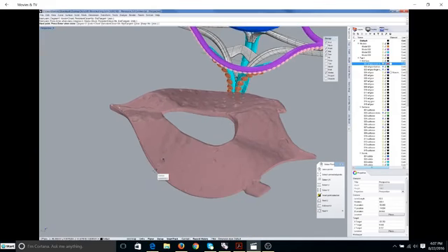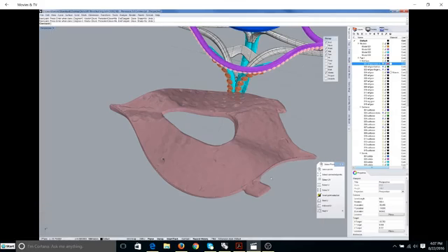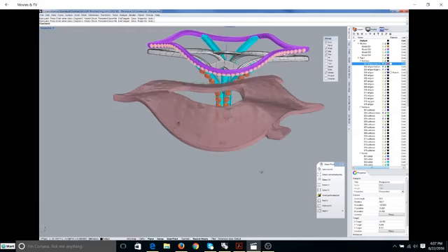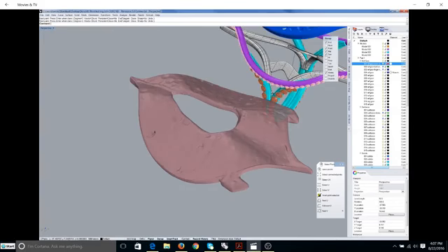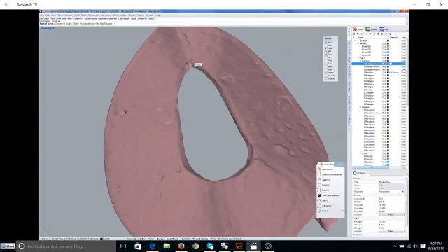And again, I'm going to do this down and dirty. This is not a Rhino class. It's just a demo to show how quickly you can go in here and create some curves and create a base surface for yourself to start to model. So there's my first curve. It's on the edge of that object. I'll go on the inside now, and we'll do the same thing.